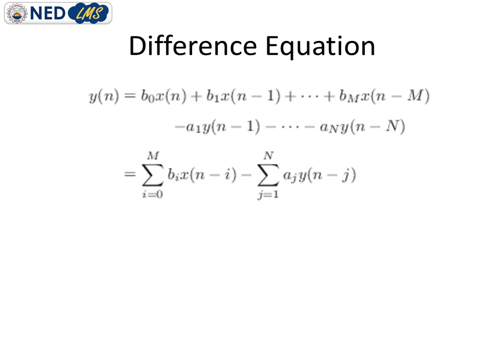So after shifting the coefficients of y, which is the delayed version of the output or advanced version of the output, to the right hand side, these coefficients become negative, because we are more interested in the actual output, not the delayed version of output or the advanced version of output. So to determine the actual output, we represent this difference equation in the standard form.